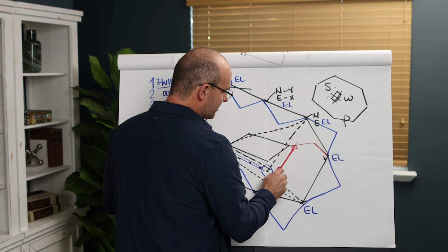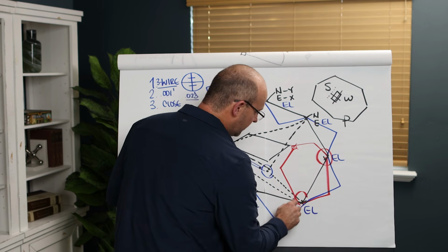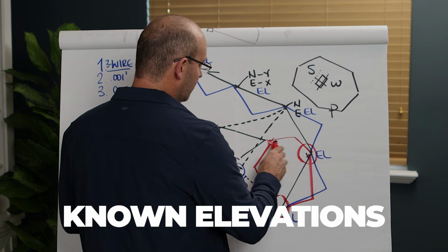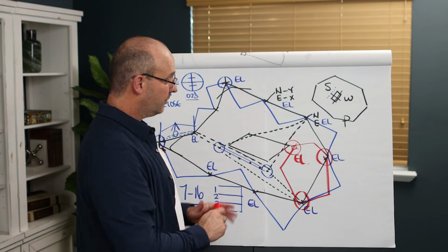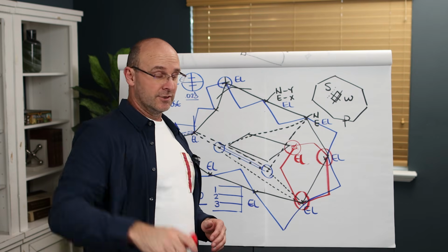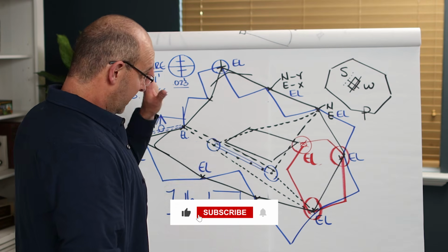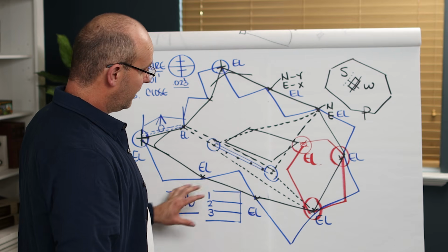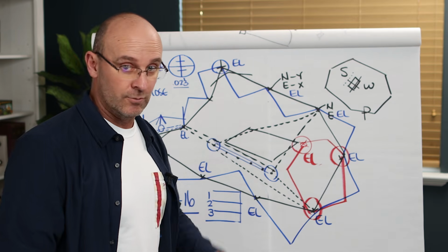Then you'll do backsight, foresight, include 2 benchmarks in that level loop from known elevations and close, and only then can you know the elevation of your new point. You cannot just do a side shot over there to it. So this level looping is how you get elevations on your primary control, and then how you would later bring it in through this process to your secondary and working control.